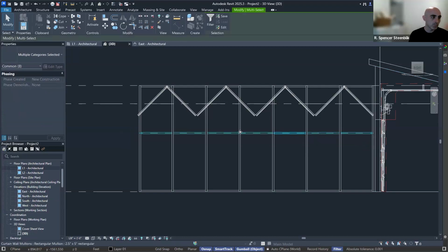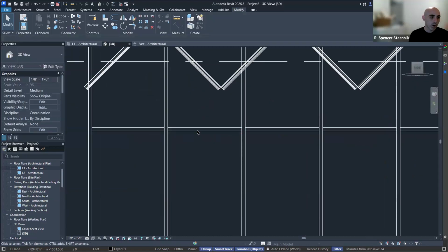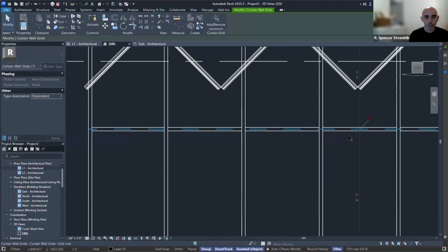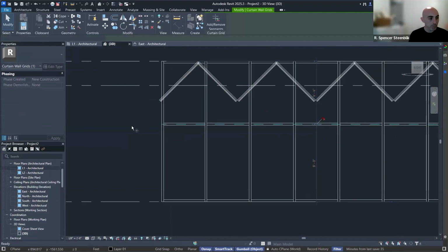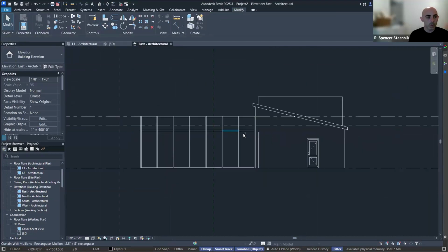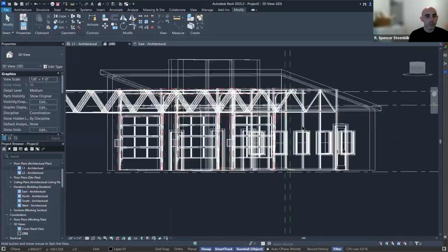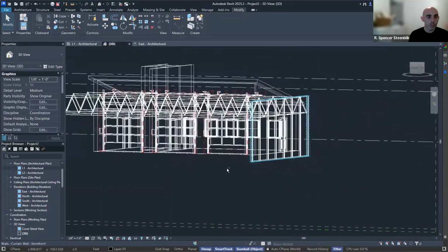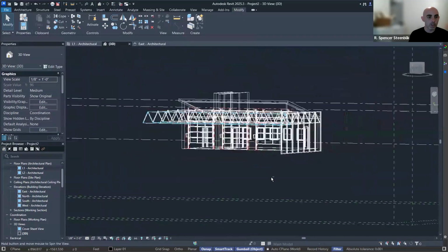What we really want is that. Oh yeah, so one of the nice things about Revit is you can tab through to select different objects. So now we've got that thing, the dashed line selected, which is where the mullions are based. And so we can unlock that and move that up, MV, and then we can move that up 2'6", let's say. Beautiful. So now we have that one wall that we wanted to develop here in Revit.